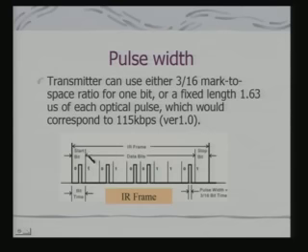This start bit indicates beginning of a data transmission, that is followed by the data bits, and then you have got a stop bit. These pulse widths are typically 3/16 of the bit time. So it is not that corresponding to the bit, it will be always on. So what we are using is effectively a pulse width modulated transmission.